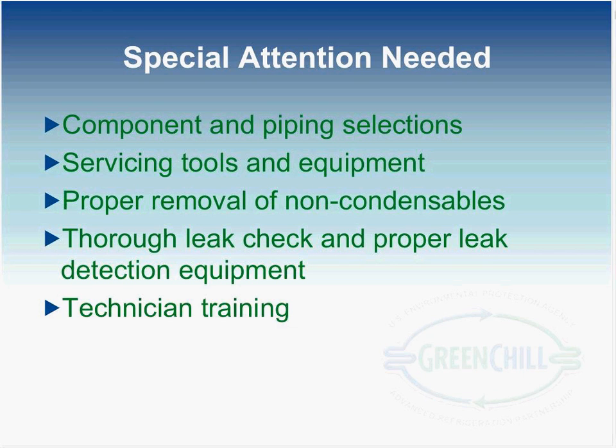Next, we'll talk about service. Most service valves today have low loss fittings and such to prevent the accidental release of refrigerant into the atmosphere whenever the valves are used, or gauges are used on servicing equipment. These types of valves are not recommended for use with CO2.